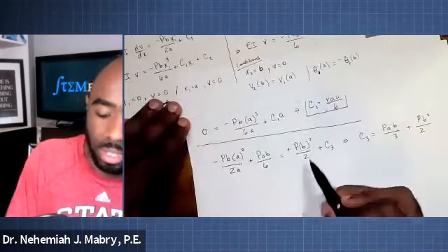So there's the last thing that we need to solve for, and that is C4. We know C3. We need to know what C4 is. To solve for C4, we really could use either of these conditions right here. We could set x2 equal to b and set the whole thing equal to 0. Or we could do the same thing that we just did, where we said v2 when x is equal to b is equal to v1 when x1 is equal to a. And because we've done things like that before, let's do this one again.